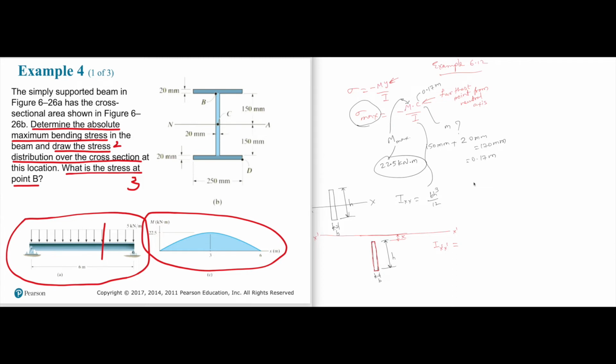There is a way we can still find that. It is defined with the parallel axis theorem. Remember that because we need it a lot in this course. According to the parallel axis theorem, we can calculate the moment of inertia with respect to an axis away from the centroidal axis. Let's call this xx.